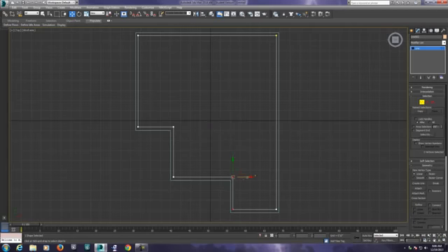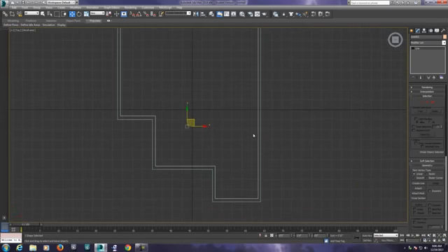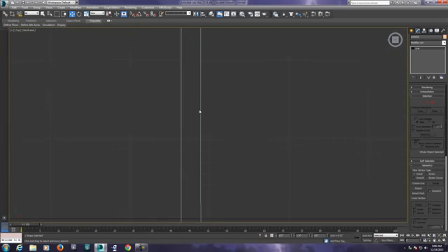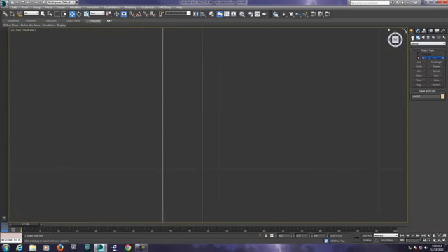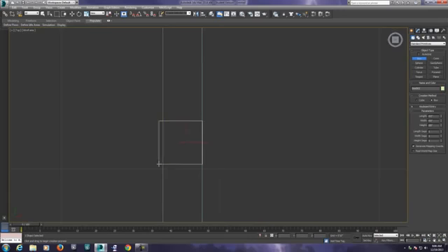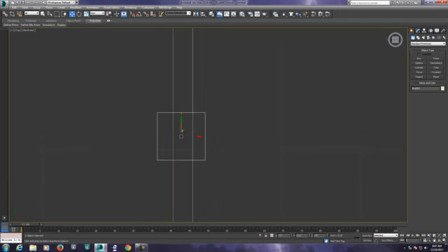And again, if somebody gave you exact dimensions, you might want to draw some lines and use some tools to lay out the actual size of the room first. And you know, between the exterior and interior walls, there's typically about a 6-inch gap. So we could test it out and create a little box here as a guide. I'm going to make this box 6 inches by 6 inches by 6 inches. And that guide is going to let me know if my walls are offset enough, and they're definitely not.